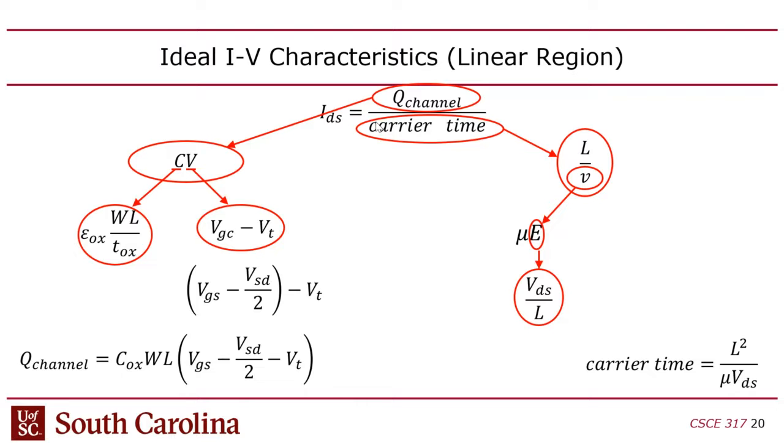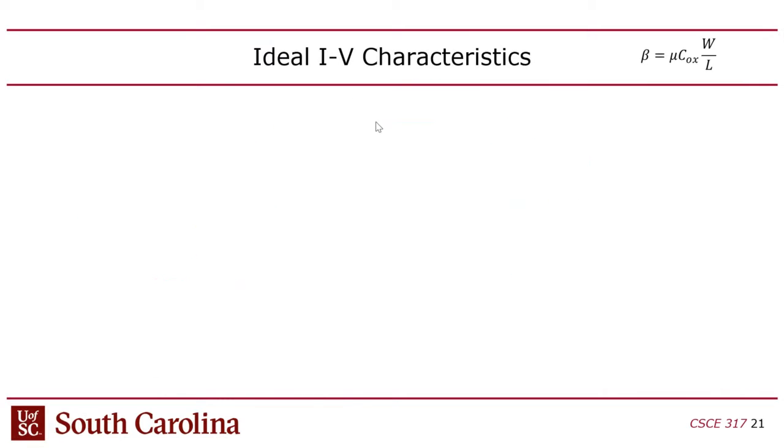Generally, if you need a powerful driver on the chip, because you need to drive a large load or a large fan out, you can just make a bigger transistor. You can make an inverter with non-minimal width transistors, and that'll act essentially as an amplifier.